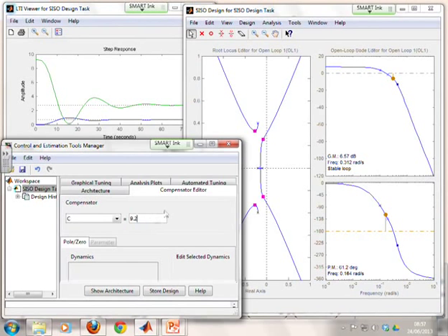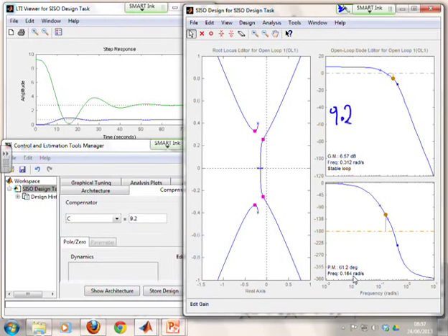You could be more precise if you wanted, but remember decimal places really make little difference. Now, what's the current gain crossover frequency? I read that down here and it's 0.164. So what I need to do now is, if I write on the screen, remind you of what my compensator will be. It's going to be 9.2 into (s + 0.0164) over (s + 0.0033), since I was going to divide by 5, so I get 0.033, that's close enough.